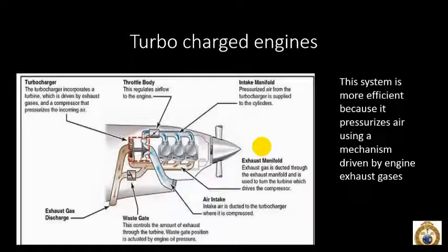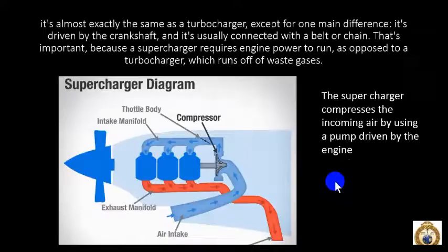It's the exhaust gases here, after closing this wastegate, kick back, and this turbocharger is connected to the turbine, which sucks in more air and packs it into the cylinders at a more rapid rate. So even though we have lower density air, now we're pulling in a whole lot more volume, a whole lot more density.